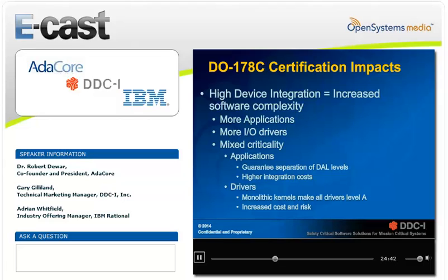A DO-178 certification of these systems poses a challenge to the system integrator to determine which of these interfaces have to be very high design assurance, and how do you separate those from low design assurance I/O interfaces.